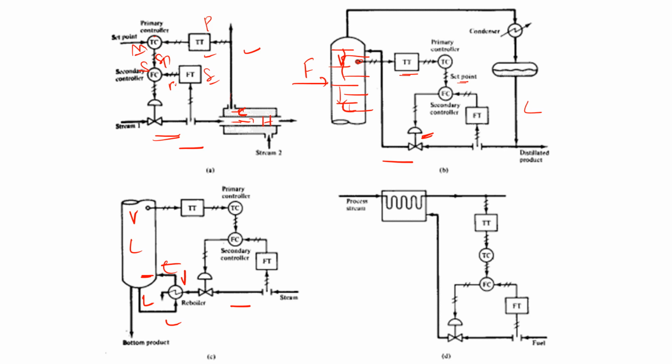Okay. So here in this case, I want to measure the temperature. So measure the temperature and take a control action. This becomes the set point. So before it affects, what you do is first, in order to have this temperature, we need to control the reboiler input. So this is the manipulated variable. So have an eye on that.